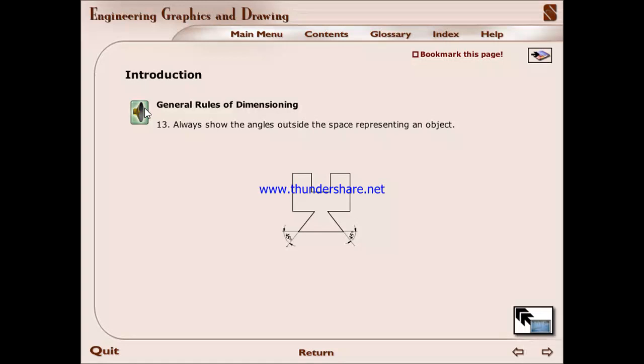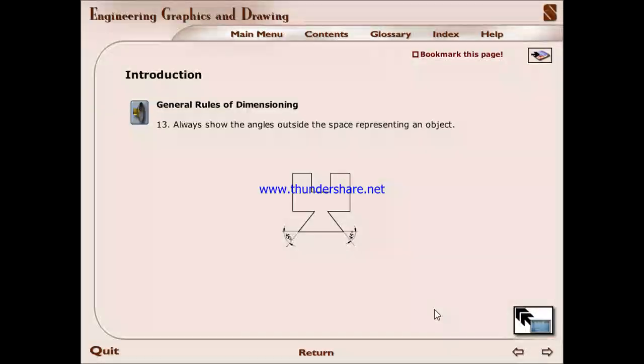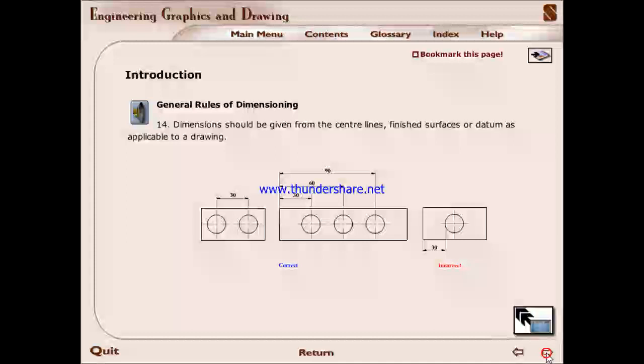Always show the angle outside the space representing an object. Dimensions should be given from the center line, finished surfaces or datum as applicable to a drawing.